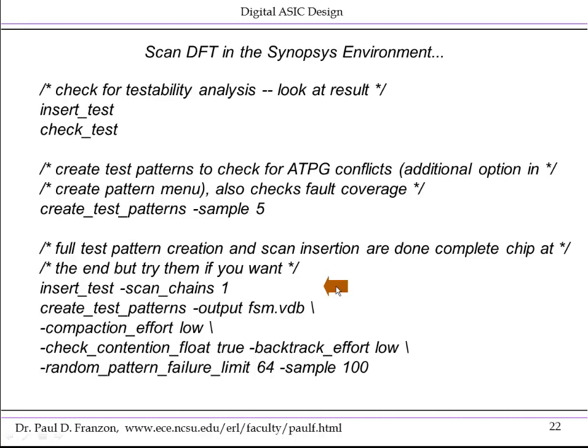Much will be dictated by a specialized test engineer, but you as the designer need to know how many scan chains are running through your design. So here we're actually inserting the scan chains, that is connecting up the scannable flip-flops. And again, here we're creating a small set of patterns just to verify that we can actually apply patterns to what we've done here.